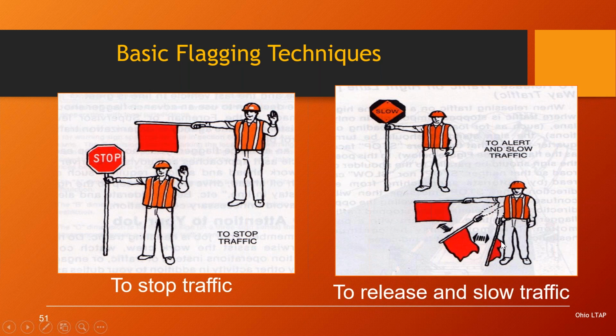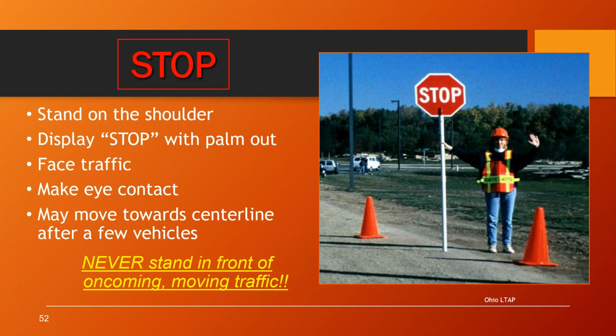And here's a picture of our flagger stopping traffic. Making eye contact with the motorist is important. And then, of course, in today's world, everybody wants to drive a pickup truck or an SUV. The problem with those in a flagging operation is that they block the view of other motorists that are